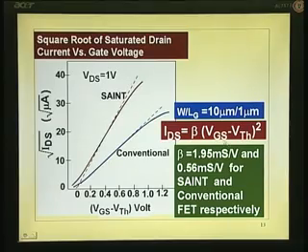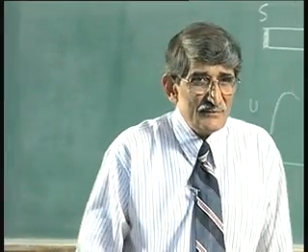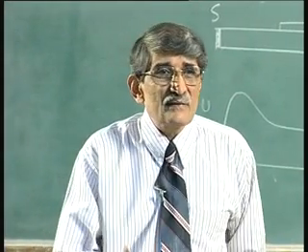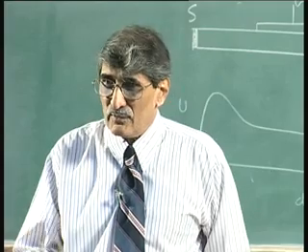Okay. Here what they are talking of is channel width 10 microns, that is the gate width, a very small device. 10 microns gate width, gate length is 1 micron, 10 micron by 1 micron. And you take VDS equal to 1 volt, the root IDS versus Vg minus V threshold voltage. If you plot, they get this sort of characteristic, linear root ID, telling you that is square law, which is what we showed: even when the velocity saturation effects are there, it gives square law.